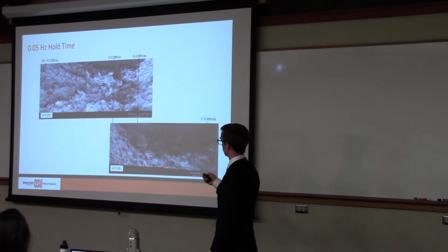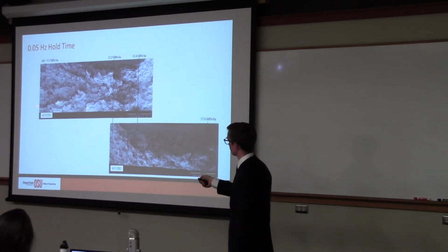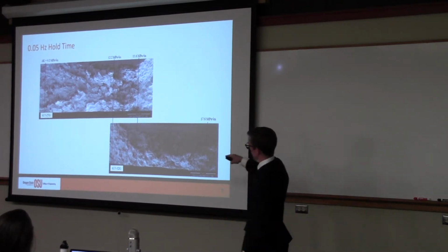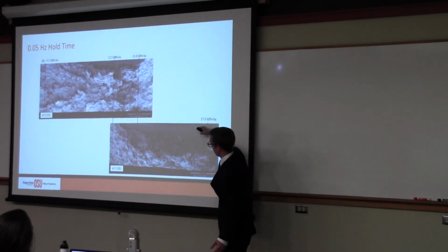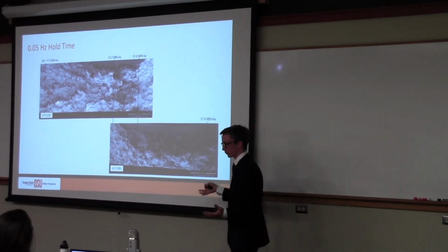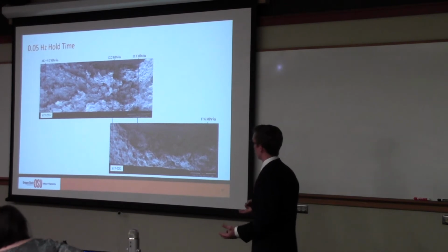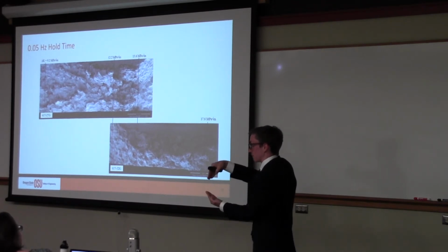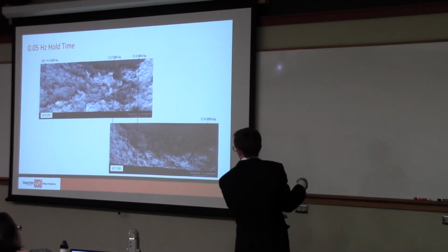We'll look at this in a couple different ways. Again, hold time samples aligned with their stress intensities, you get all the way up to 17.6. And I know that's a little bit darkened out because of the compliance of the sample. This is actually the edge of the sample. And we had a better close-up of it. What you'd see, maybe something that I'll draw on the board later, is that the sample's very compliant and getting very thin as the crack is opening.